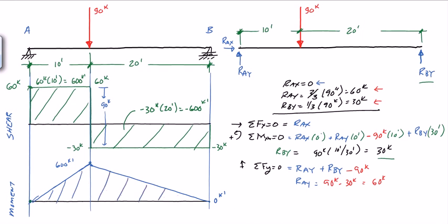for a point load. And a few things you can look at here. First of all, when you have just point loads, your shear diagram will have a bunch of horizontal lines like this, and there'll be different numbers depending on how many point loads, and the moment diagrams will have slope lines like that. So let's take this to the next example, and let's do a uniform load. Same beam, but let's go ahead and throw 2 kips per foot on the beam, and let's see what that moment diagram looks like.